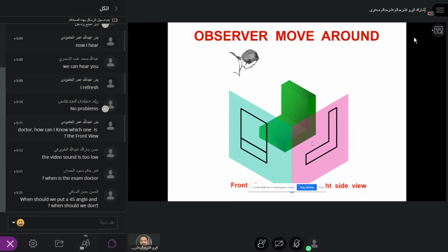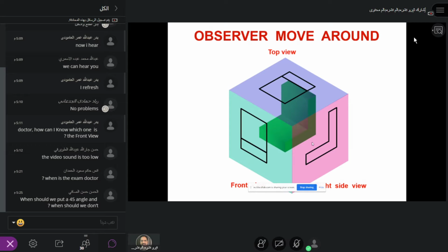Then you go to the top and watch it from the top side and project those surfaces, and you can see those projected lines. So now this is what we call the glass box method. Just imagine you put a glass box with 3 dimensions as shown, projecting the surfaces and the edges on the glass box, and then you expand it.